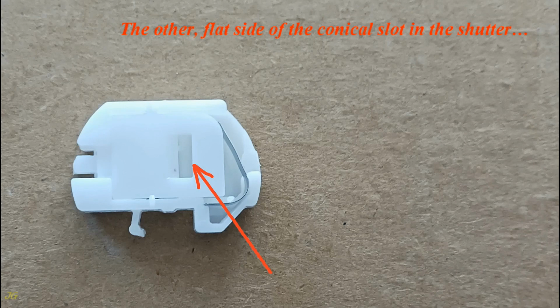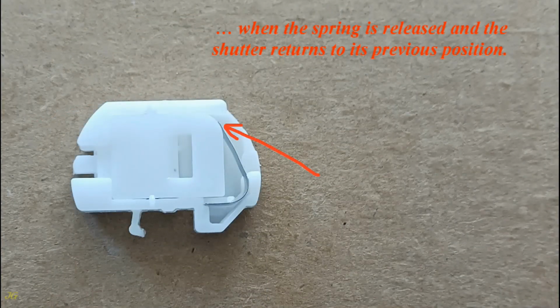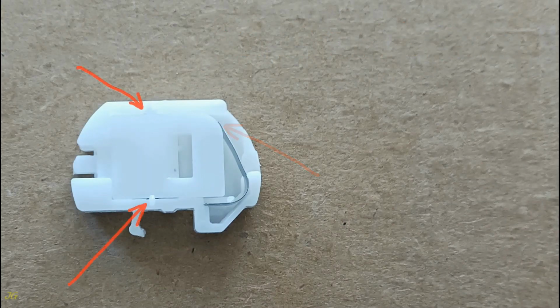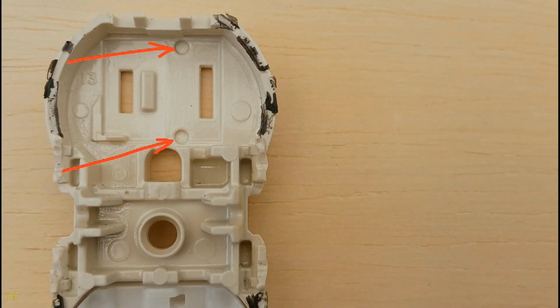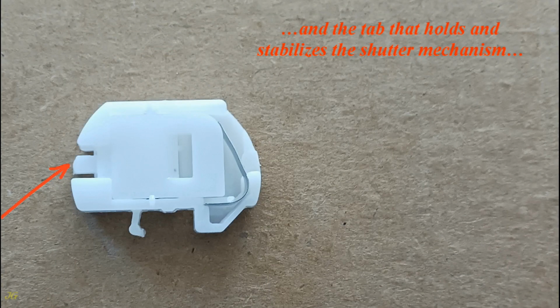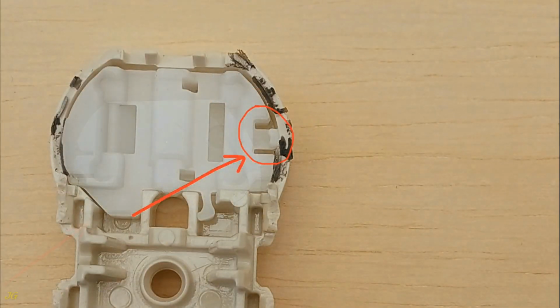The other, flat side of the conical slot in the shutter holds the shutter in place on the flat side of the conical post in the front base of the receptacle, when the spring is released and the shutter returns to its previous position. The front pair of pins holds the shutter body in the front receptacle base, and the tab holds and stabilizes the shutter mechanism from the side in the front base of the receptacle.